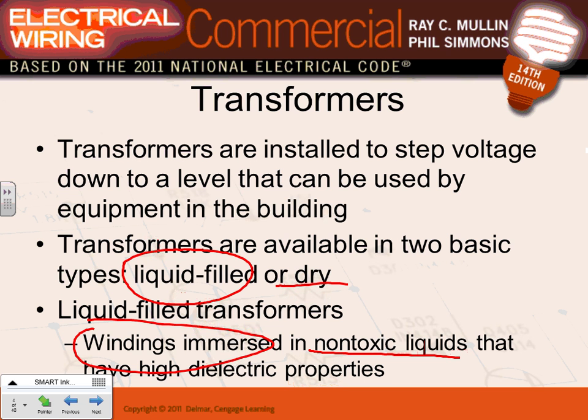If it's dry, the windings in transformers get hot when they convert power, so you need to cool them, either by natural cooling, or if they're oil, the oil will help in cooling these windings. What you guys are going to be dealing with typically, for the most part, is dry type transformers. When they say 2500 kVA, that's a dry type transformer. When Excel comes up with a 20 megavolt amp transformer, you are looking at a big fat oil-filled transformer, typically mineral oil in this case.